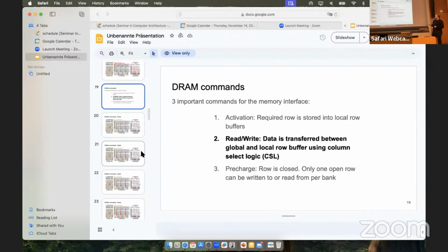So in the pre-charge command, the way sector DRAM changes it is that we specify which sectors we want opened for the next activation command, using some of the empty bits in the command. But if we have a lot more banks, then the pre-charge command needs more bits in and of itself, and then we don't necessarily have the same leftover information that we could use. So that becomes more complicated.